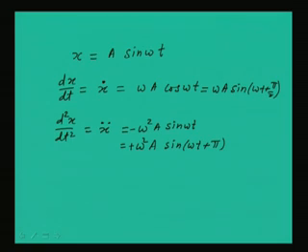So this particular quantity which is coming, they are representing the phase. So you can see that the velocity term is having a phase difference of pi by 2 or 90 degree with respect to the displacement. So here this velocity is leading by pi by 2 with respect to the displacement. Similarly, this acceleration is leading by 180 degree or pi radians with respect to the displacement, and this particular thing can be shown in graphical form.